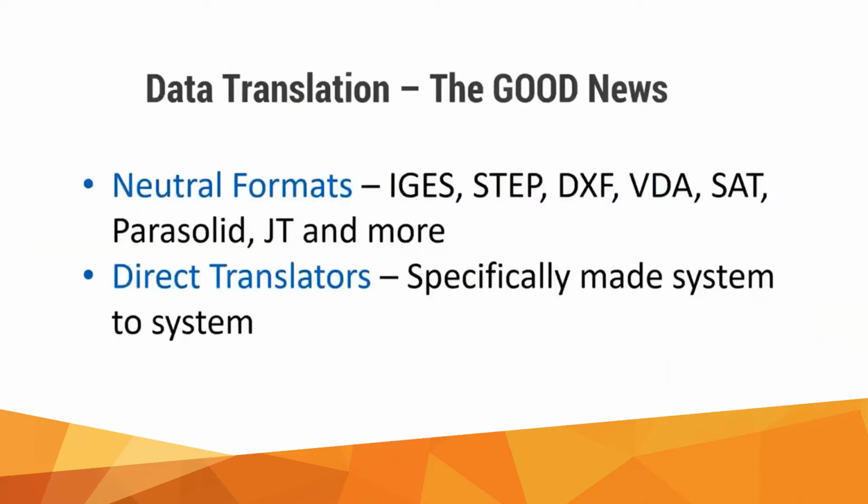The good news about translating data is that part quality is as good as it's ever been. For the most part, the days of the terrible tangled IGES are way behind us. The preponderance of solid modeling has led to better geometry, and the translators themselves are also better. Many different types of neutral file translators exist to boil geometric data down to common elements that the next system can then read, many more than just IGES and STEP.